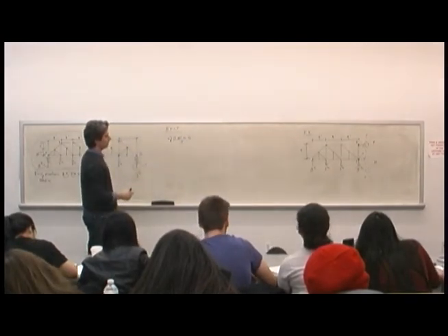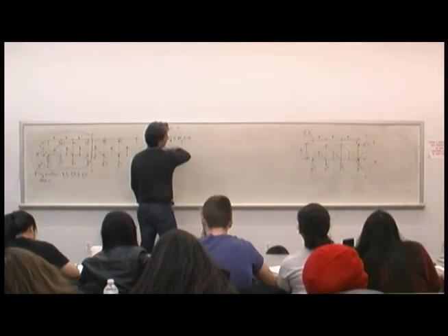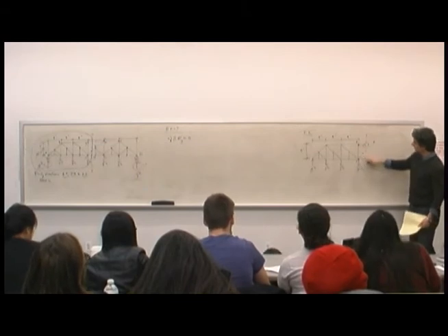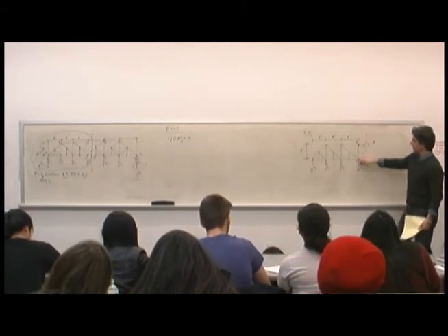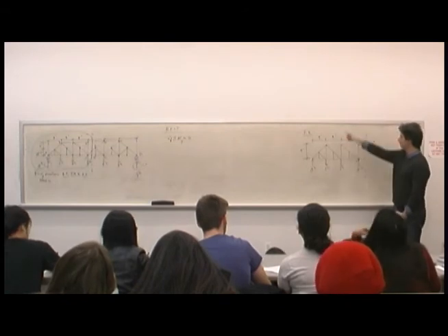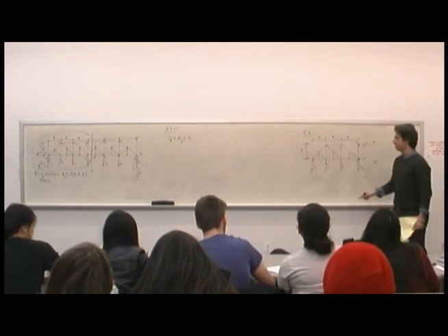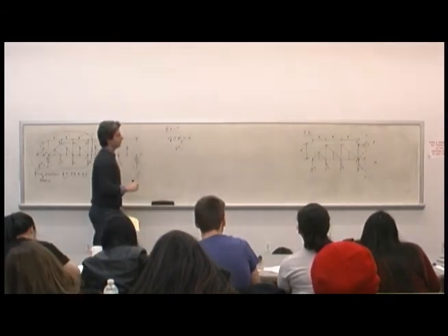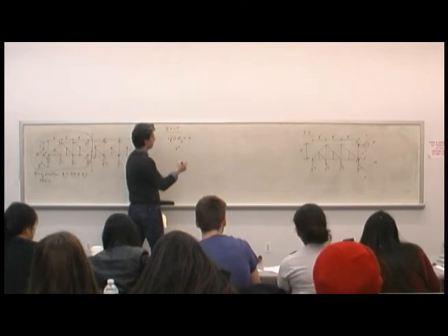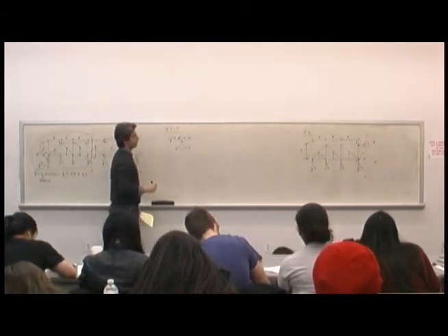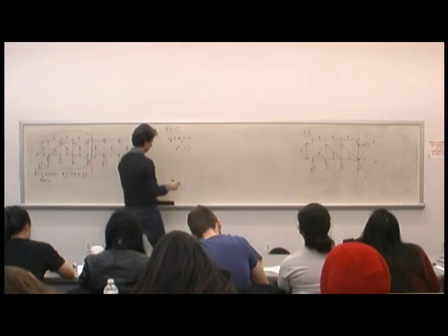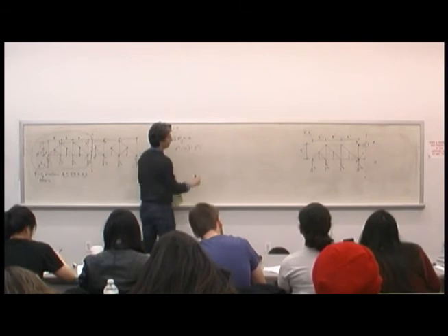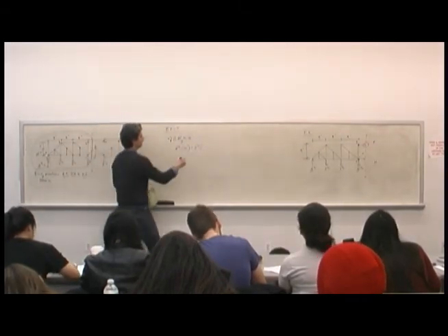So what do I have? Let's start with the 8 kip force. If I'm spinning this way, you put yourself at that spot, so all these vectors go through you, and the 8 kip force is spinning this way. Positive. So I have 8 kips, and the distance is 12 feet. The 2 kip force is negative, and its distance is 8 feet.